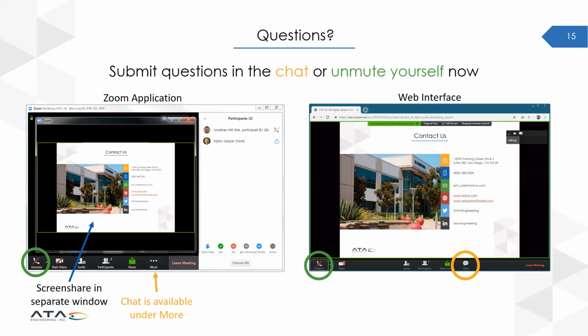You can see a sawtooth effect if you've got triangles and quads near the edge of a structure. Typically triangles are kind of stiff, and a lot of times people really like to avoid linear triangles in stress problems or structural use. Now there might be some exceptions, where people are trying to transition meshes or do different things with the triangles.